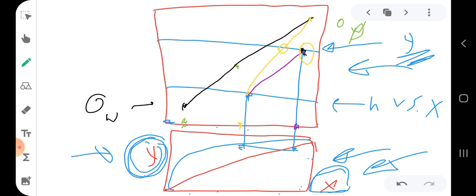Okay, so we will see this point I have here. I am on the vapor line, so this is why I move horizontally until I reach the 45-degree line. Then I move vertically until I reach the 45-degree line. Then I move horizontally until I reach the equilibrium curve. Then I move vertically until I reach the liquid line. So this will be my second point.